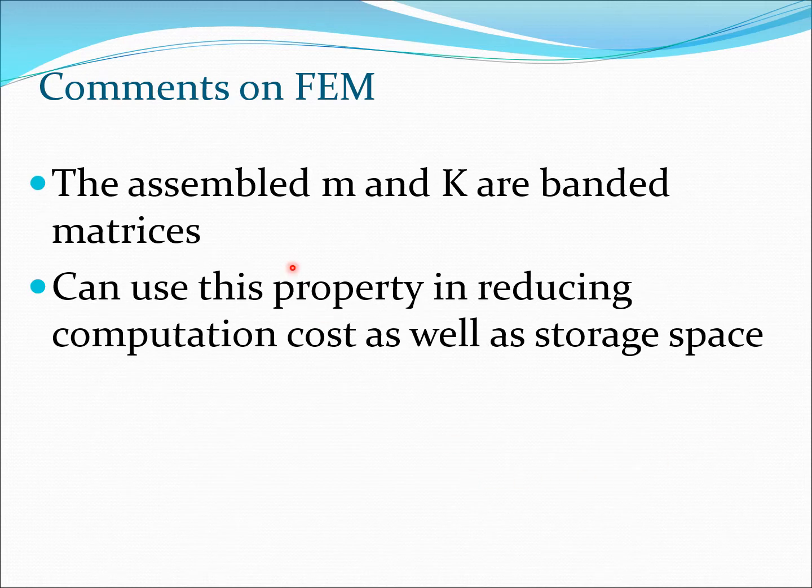We also saw that once you assemble the M and K matrices, they come out as banded matrices. So some of the terms on the side or very off diagonal parts of the matrix are 0. Now this property can be used in reducing computation cost as well as storage space. There are some books by Bathe which discuss this in detail.